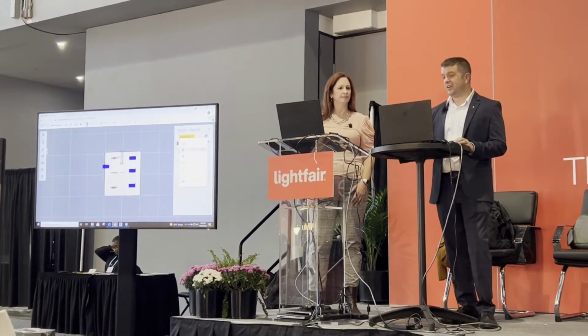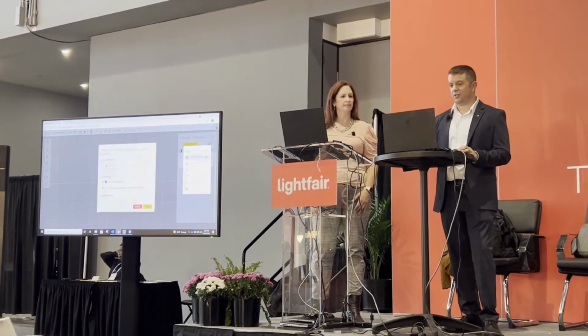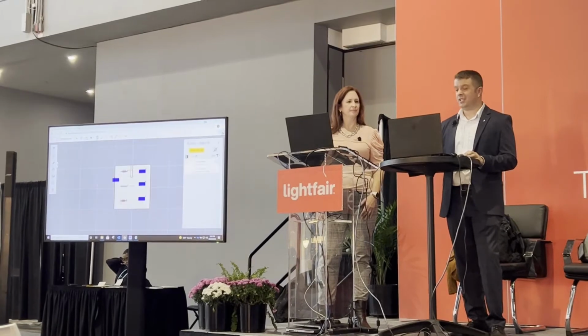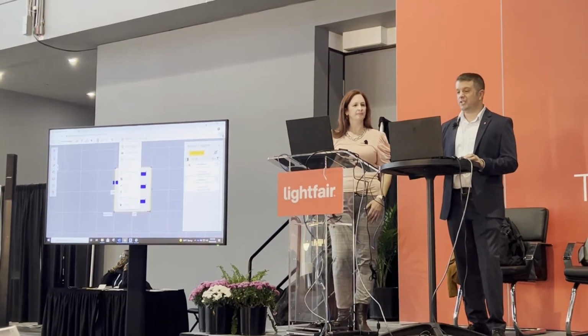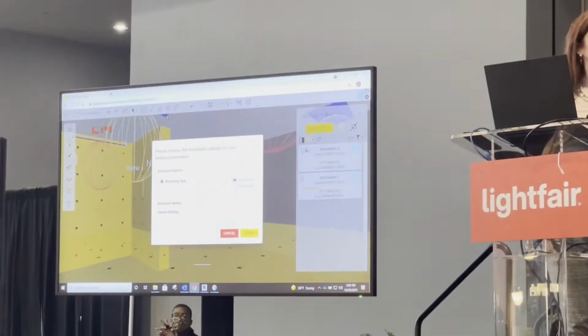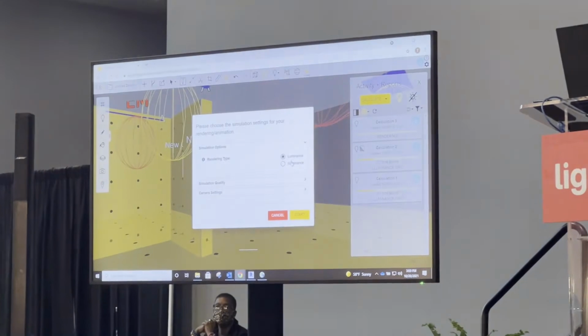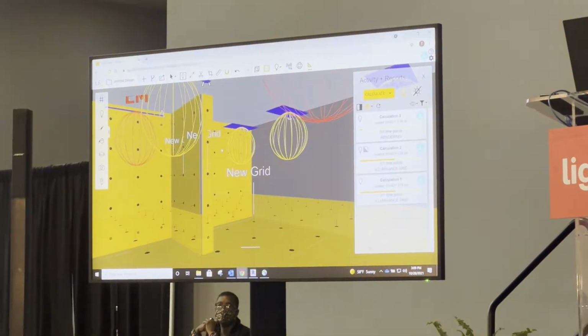So I'm going to go here, I'm going to calculate grid illuminance. I'm going to run my normal. Calculate grid illuminance, emergency only. Let's go into our 3D view here. Let's start running some renderings. Let's do illuminance rendering. And we'll do an illuminance rendering.